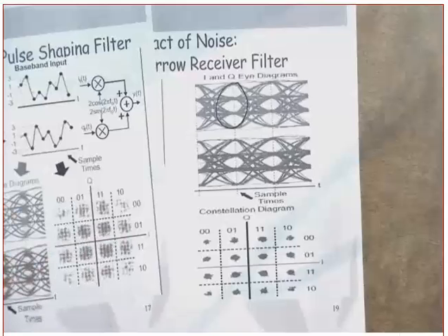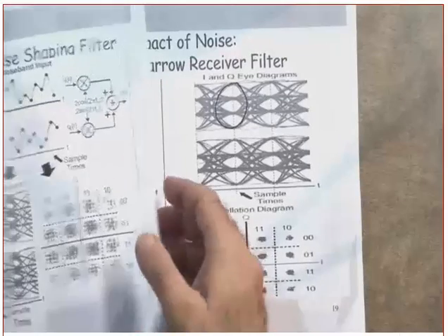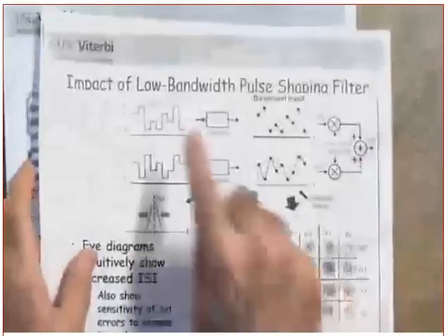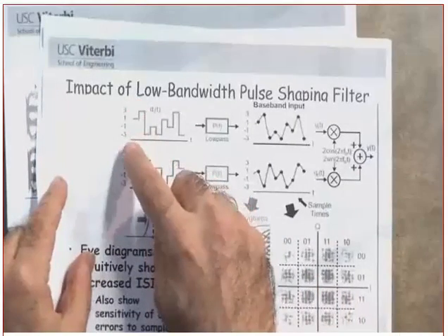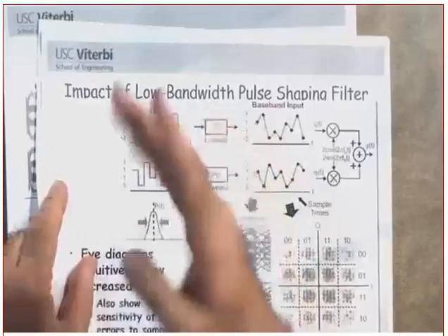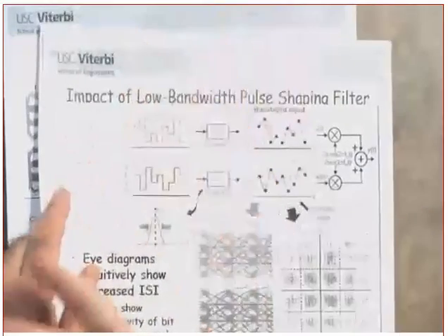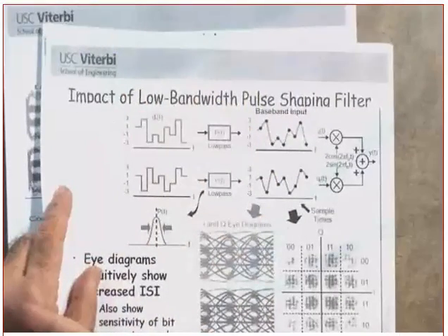Yeah, what is it? So, the top of it is, let's say, -1, and the bottom of it is 1. It depends on what we are using here. The levels are +1, -1, +3, and -3. So we have how many levels? We could have 4 levels, 2 of them on I, 2 of them on Q.